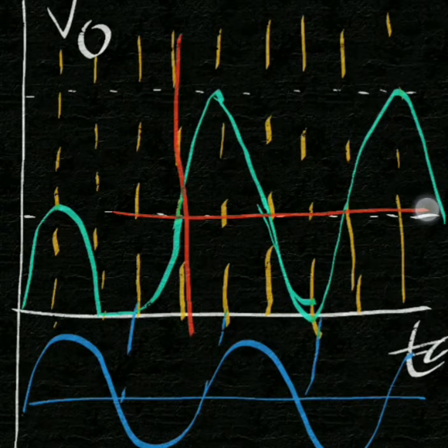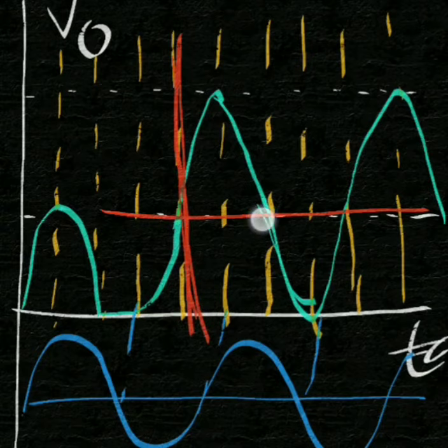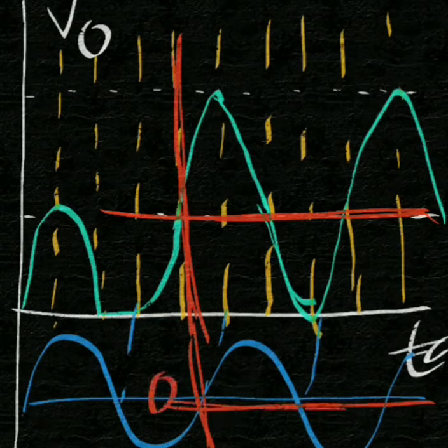At this point if we analyze, this was 0 and here it is Vm. The signal is the same, the shape is the same, the only difference is the DC level, which is shifted upward by Vm, and so we can say that this is a positive clamper circuit.